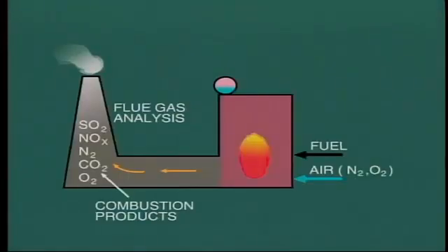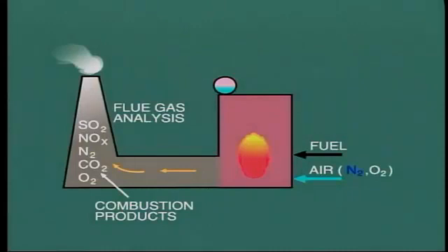Actually, this nitrogen does not enter into combustion and does not help at all in the combustion process. Rather, the inverse, in that it contains a lot of heat and carries this to atmosphere. However, there's nothing we can do about this, as we need oxygen, and the only practical way of acquiring large quantities of oxygen is from the air which surrounds us.